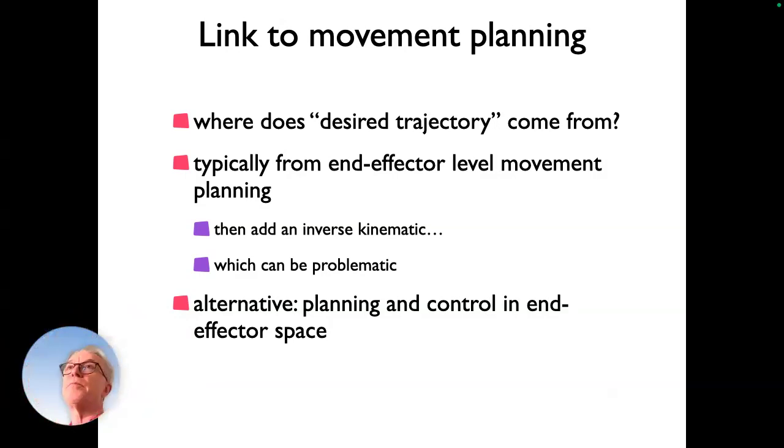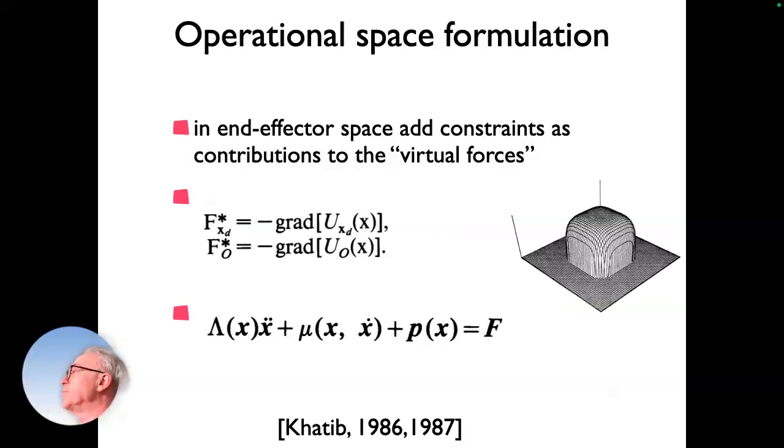Sometimes you might want to not separate that, and that is actually what Khatib did. So I'll just point that out. Khatib's original work was a little richer than what we talked about, because we just talked about the vehicle case. Remember that in the potential field approach, he had this idea of having gradients of potential fields be virtual forces. And his idea was to insert these forces into the operational space equation of the dynamics of the arm, and therefore it would be integrated with control.